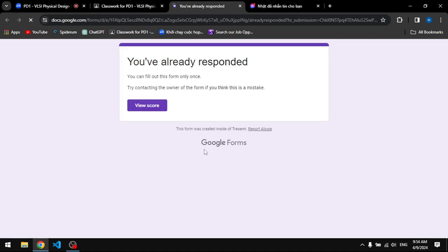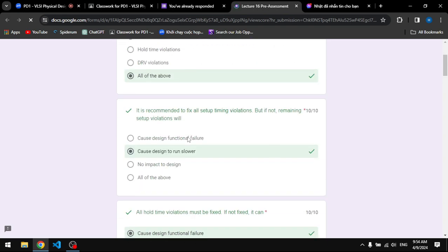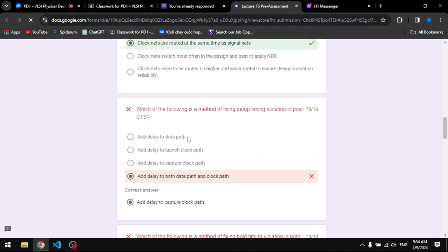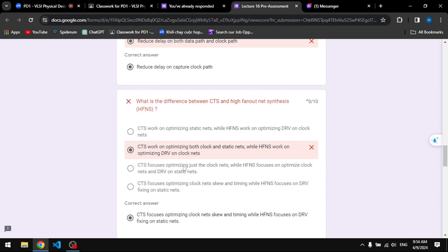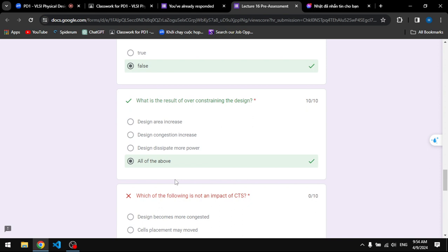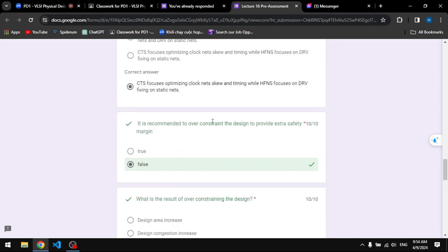Dummy load insertion. This is a cell you use right away to fix your CTS timing. It is used as a dummy load to balance out these branches, inserted along with the rest of them. So this is actually being used, and it does not refer to a spare cell. Spare means something you insert for future use, for backup. That's called a spare cell. So let's be clear on the spare cell and dummy load insertion.